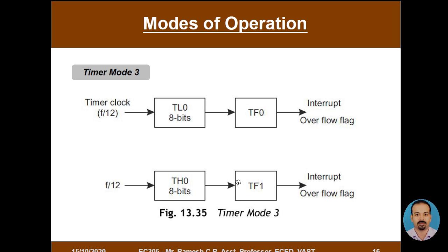That is why we say that if we make use of timer 0 in mode 3, then timer 1 cannot be used for any timing operations. Since it does not have its overflow flag, we cannot make use of its timer registers overflow to implement timing information in our program. So that is about mode 3 of operation. This is the rarest mode that is used in timer.